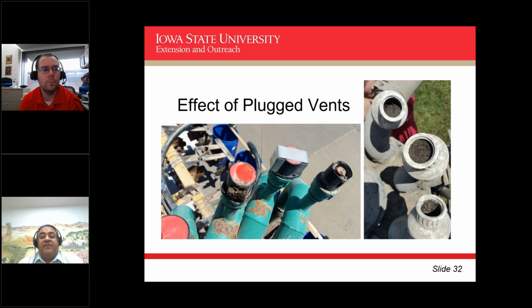When we are applying manure in fall, sometimes we are dealing with very cold conditions when we get done with manure application. We get done in the season and we just go and park our equipment. Next fall, when we start out, or the next application routine when we start out, we need to watch for these vents. If they are plugged up, they will not allow the discharges to the hoses to discharge equally.